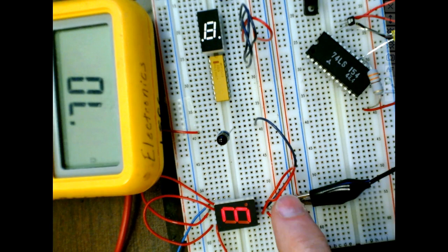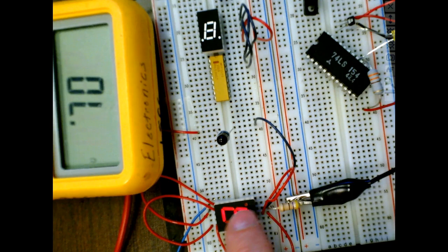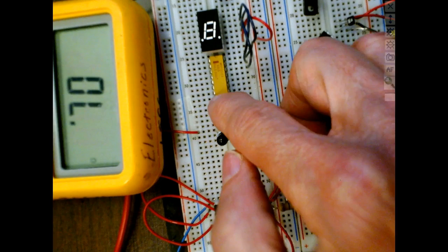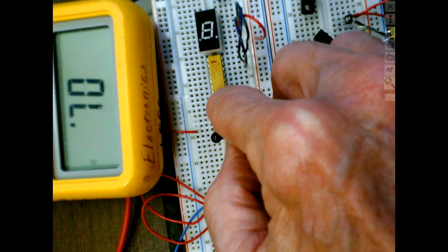So instead of using one resistor, what happens when I use one resistor? Well, every time I turn on a segment, all the other segments do what? So what we normally do is put one resistor per segment, and we put it in the control pin, not in the power pin. We put it in the control pin. That makes sense? A 330 ohm is usually what we use, 330 ohm or 470 ohm. You see those used a lot.